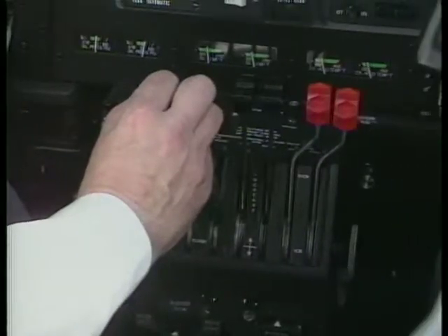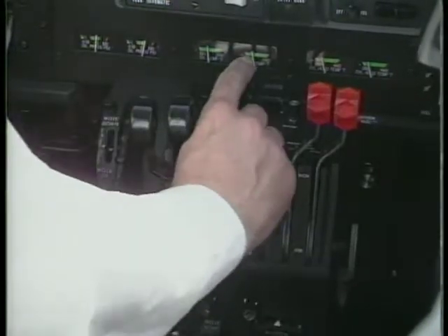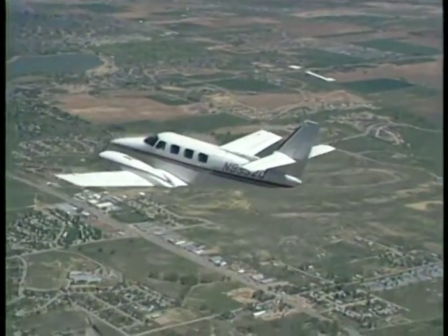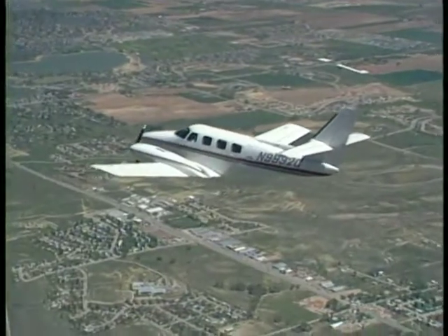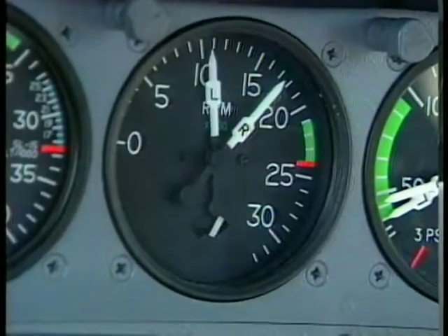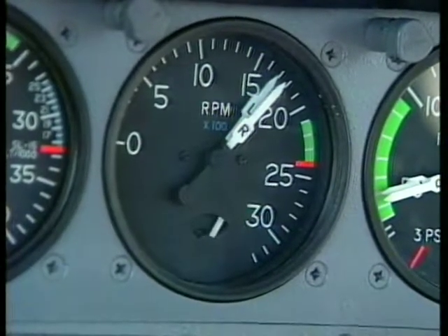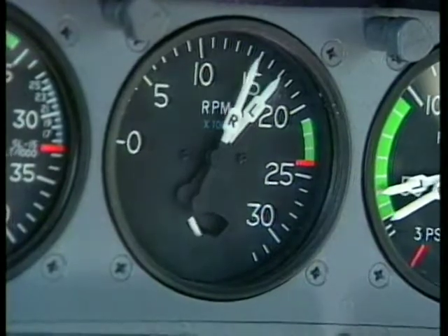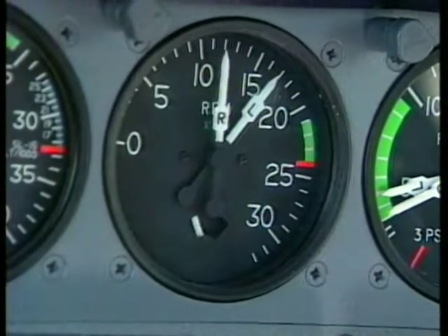The propeller feathering check is another unique consideration for multi-engine airplanes. In flight, this system lets you move a propeller to a streamlined position to reduce drag in case of an engine failure. The ground check involves moving the propeller control into the feather position, watching for an RPM decrease, and then moving the control back to the normal setting. It's very important not to let the RPM go below the limit specified in the pilot's operating handbook.